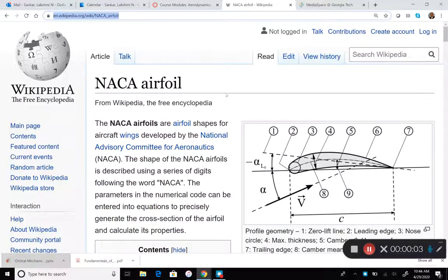In the previous lecture, we talked about airfoils, airfoil nomenclature. We said that an airfoil could be thought of as a chord line, which is simply a straight line that goes from the nose of the airfoil to the trailing edge. Then to the chord line, you add a camber. Camber makes it asymmetric. If you don't have any camber, it's a symmetric airfoil. Then you add a thickness normal to the camber line by convention to add the thickness. So an airfoil is made of three components: chord, camber, and thickness.